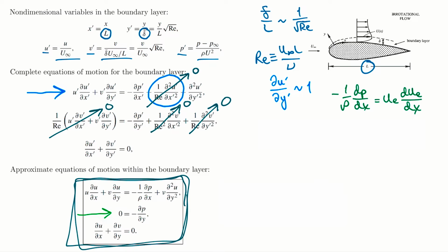So that's just an equation we can use to solve for the pressure gradient. Now, we don't actually have to use it to find dp/dx at the edge of the boundary layer. You can, as a first approximation, use it to solve along the surface of the body and neglect the existence of the boundary layer, because the error goes to 0 as the boundary layer is really thin, and we've seen that approximation already works very well. So you solve that outer problem first, and then you'll get that dp/dx term from that solution of the outer problem.